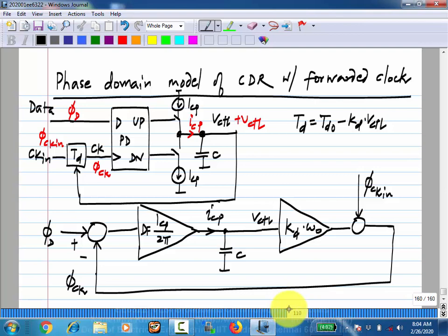Now we can add more things here. For instance, these current sources used to make the charge pump will have some noise, okay. So we can also add that to see what effect they have. I will call it IMCP. So that will be the current noise of the charge pump, okay, effective current noise. Now we have two sources which are switching. We will discuss that. I have modeled the entire noise as an additional current at the output of the charge pump, okay. So now please calculate the following in this.